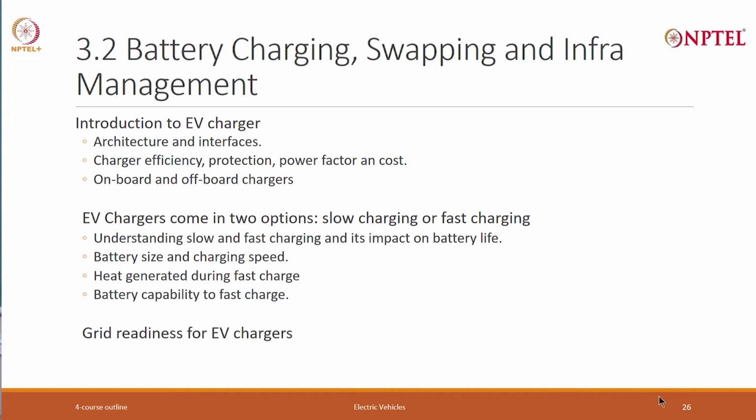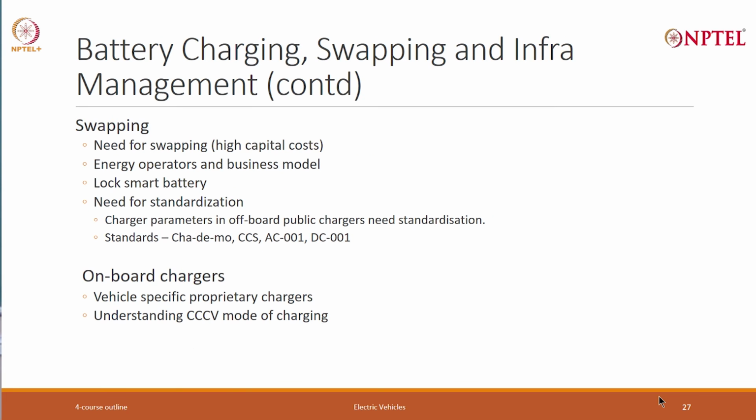Understanding slow and fast charging and the impact on the life of the battery. We will talk about battery size and charging speeds, heat generated during fast charge and the battery's capability of doing fast charge, and finally grid readiness of EV battery.